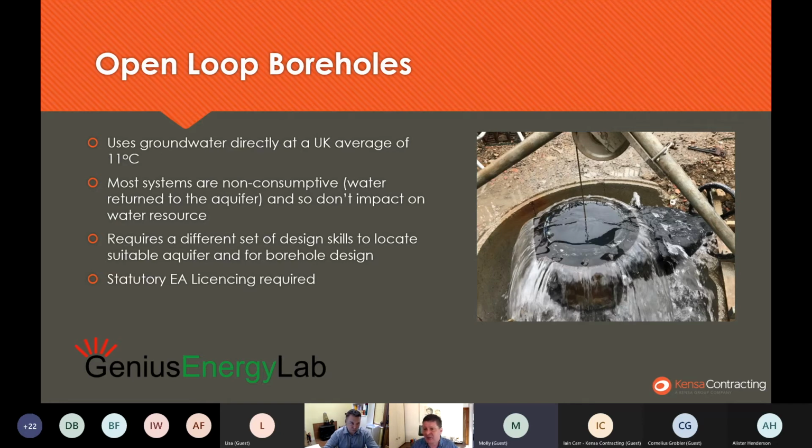And yeah, you will find that large part of Scandinavia, for example, they do some very interesting drilling methods because they've got a very hard rock condition. It's generally quite full of water. And then rather than grouting the boreholes, as I was describing earlier, with that cementitious grout material, they actually just hang the pipes in the water in the borehole, which makes a very inexpensive drilling solution. So yeah, we are both blessed and cursed to an extent in the UK with our geology.